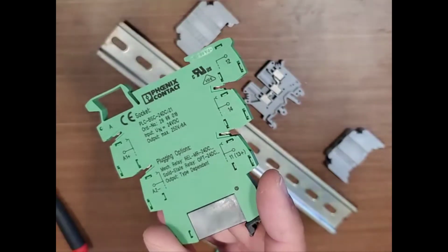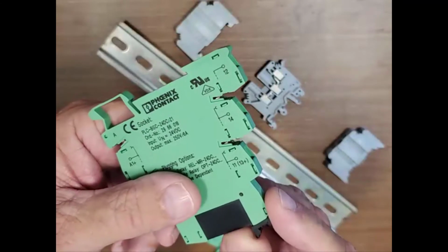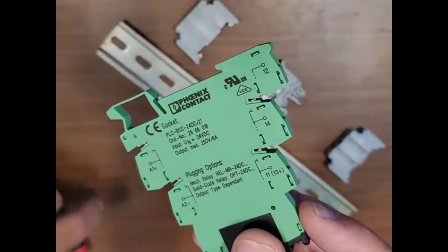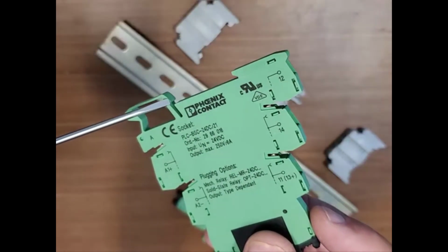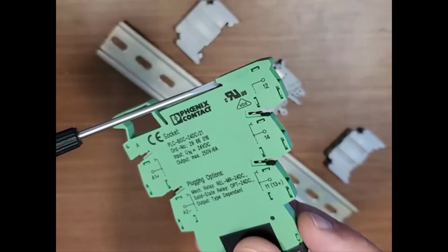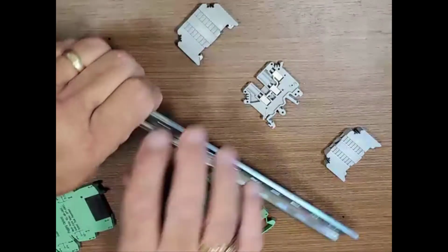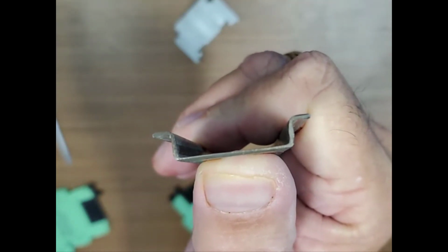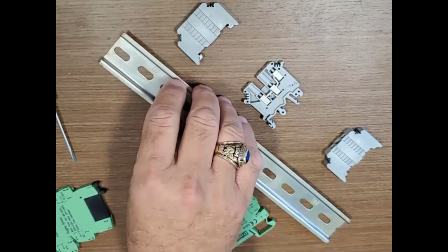This happens to be a relay socket with a relay here at the top, and this thing just snaps in and out. But the feature of interest is there at the bottom with these plastic features that allow snapping onto the DIN rail. And so the way that works, let's take a look at the DIN rail first and see if I can get this to focus. You can see the cross-sectional shape. It's a 1 millimeter thick stamped carbon steel part.